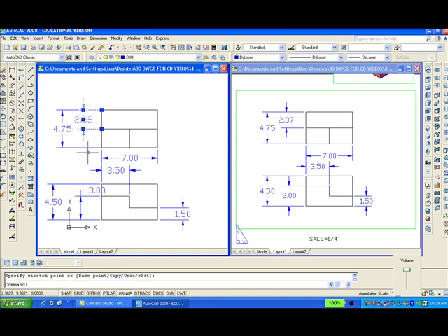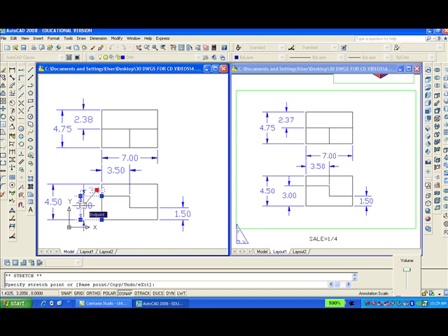Pick a point there. That looks better. And I can do the same with this one. With the grip, grab it and move it where I want to put it. Like there. Hit escape. Or I can even center it better since the O-snap is off. So that looks better.